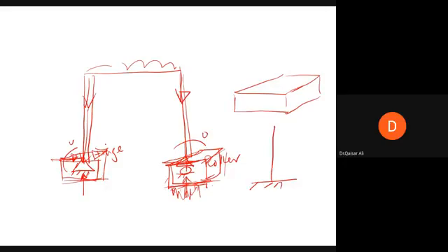whenever we say that it cannot offer resistance, we mean to say its response to the design load. So for the load for which the structure is being designed, if this pad is unable to offer resistance, then it will be treated as a hinge support, because this cannot offer bending moment resistance. And how do we know whether this will offer bending moment resistance or not? For this we will have to design this support.